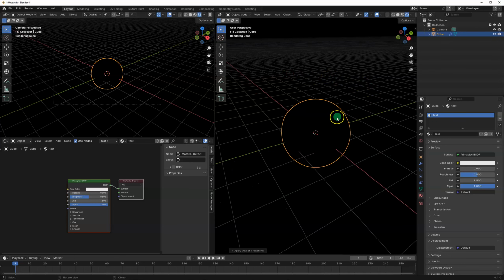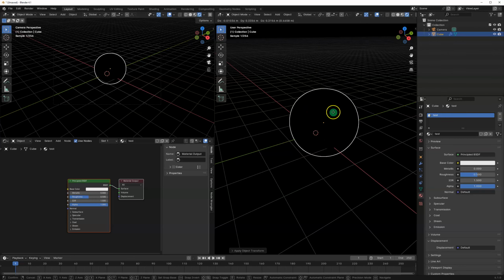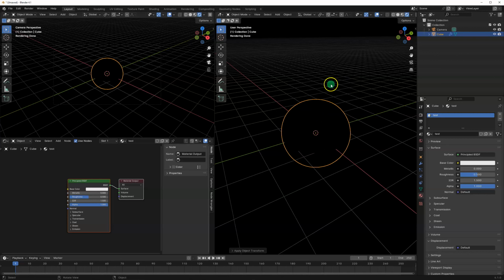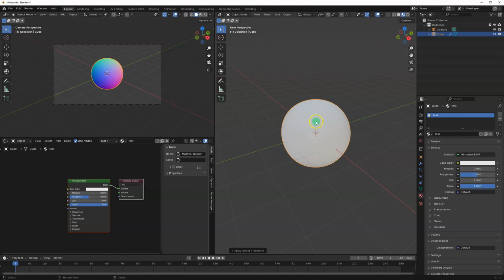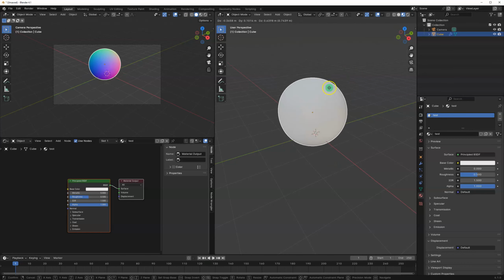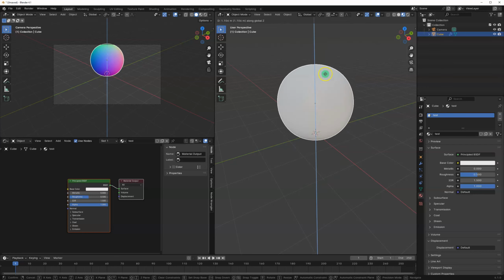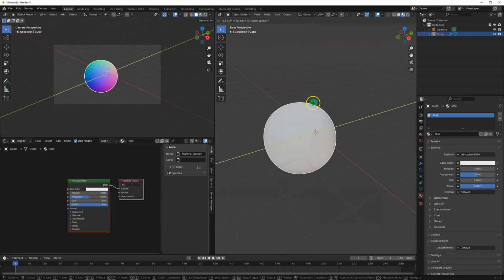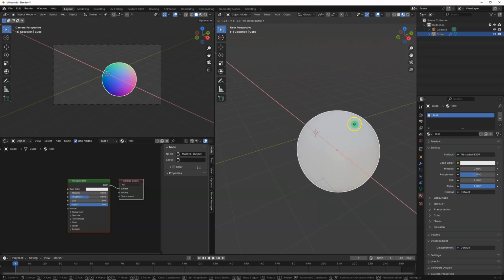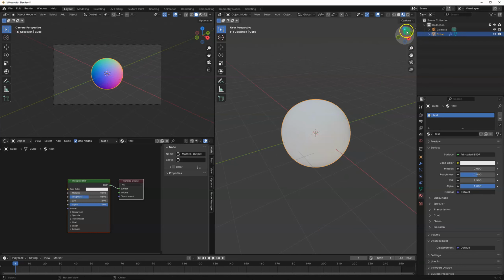Okay, so we can move things by pressing the G key, and we can move our objects. I'm just going to change the rendering mode. So if we come in here, we can press G, move it around freeform. We can press the axes like the Z, and we can move it in the Z axis constrained. We can press the Y, and move it in the Y, and we can press X, and it'll move it in the X. And you'll note that corresponds to this dialog box here.